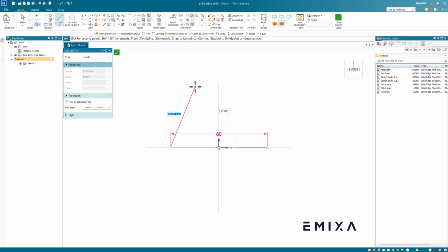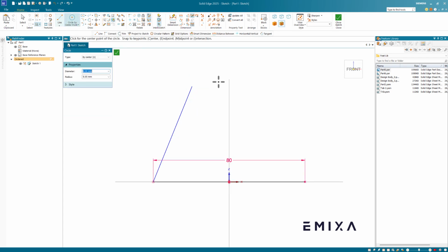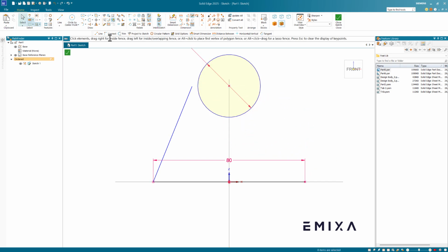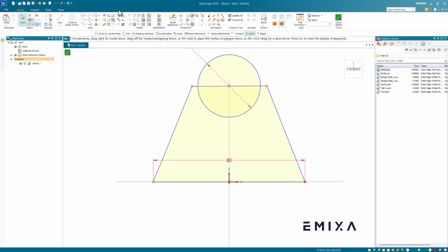and I've got a little shape I'm going to do, so I'm going to go with that. My handlebar with a grip on is going to be about 33mm diameter, so that's the shape that I want. Let's press escape to come back out of there, and let's go up across. If I hover over that, I kind of weight that up, and that's going to make sure that that's good to there, and then I'm going to go across.